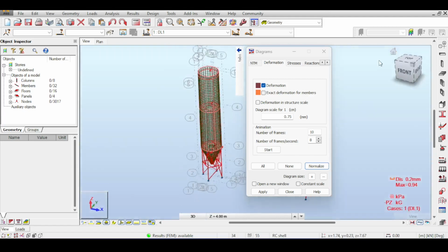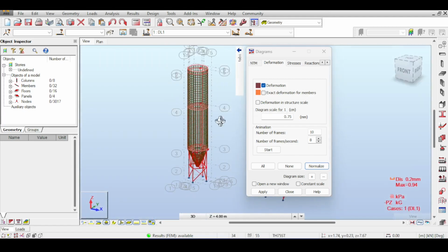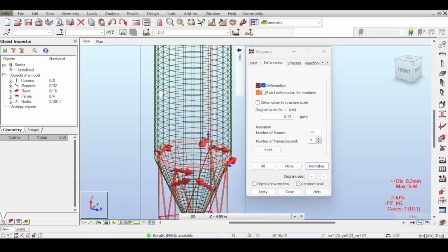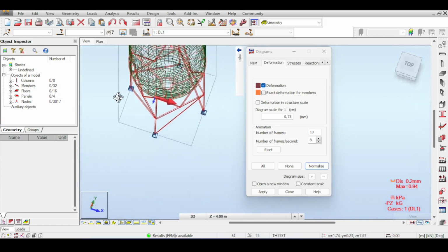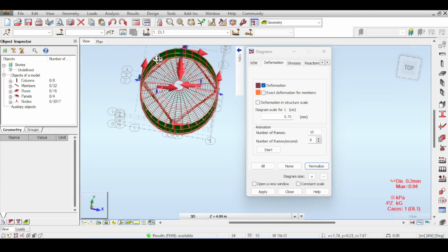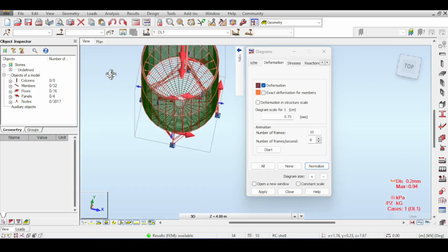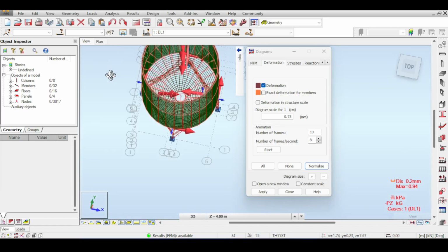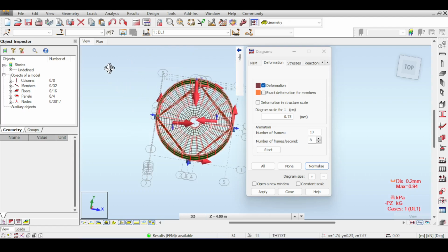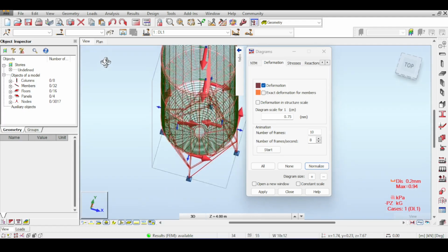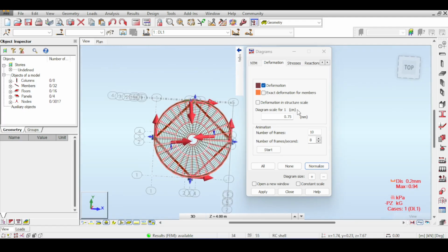All right, so this is why I think the advice of our dear subscriber, Nia Sapai, comes into place. You see, he advised to make a ring beam around the silo. Now, this would make the deflection of the silo uniform, because if you have a ring beam, then all the elements in the silo are confined with the same stiffness. So once again, a shout out to our dear subscriber, Nia Sapai, whose advice would come in handy here. I will leave it as is, but, well, at least you have an idea now.